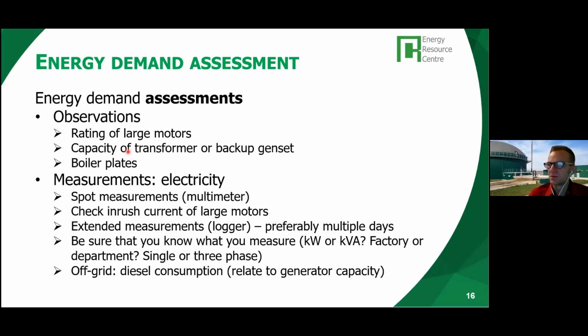It's important to know if there's transformers or backup generators. What is the capacity of those? As that will give you an indication of the required generation capacity of your energy production system. And if there's any boilers, have a look at the plates, maybe they're showing the capacity, let's say either in tons of steam per hour or in kilowatts, megawatts.